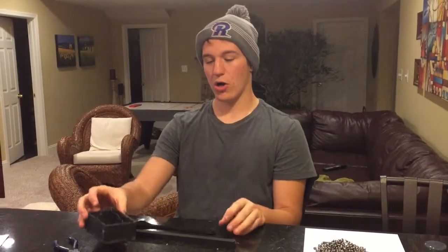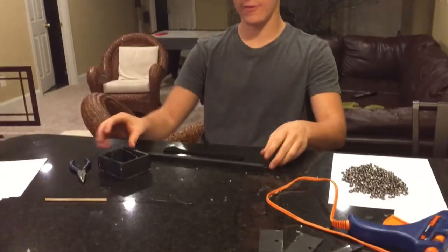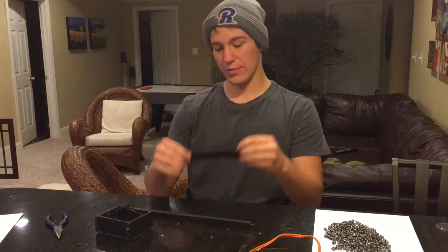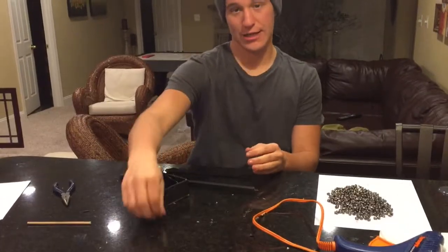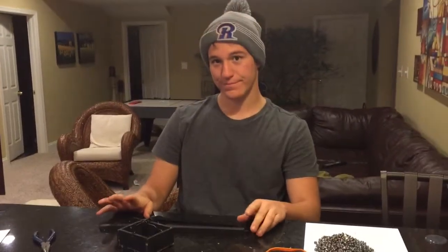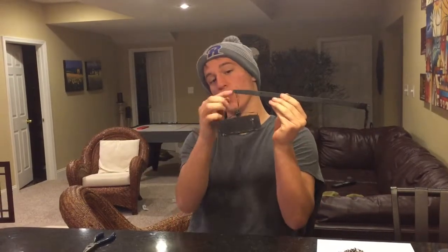All right, we're going to take all our separate components for the lever, and we're going to put them together. So the pouch, the counterweight, the wire that attaches the counterweight, and the lever itself. This is what it should look like roughly, with your sling attached to the end that has the finger, and your counterweight attached to the end that had the hole. Next, we're going to put all our lead shot, which is what we're using as our counterweight, into our container, and then we're going to build the whole trebuchet and show you what it looks like when it's done.